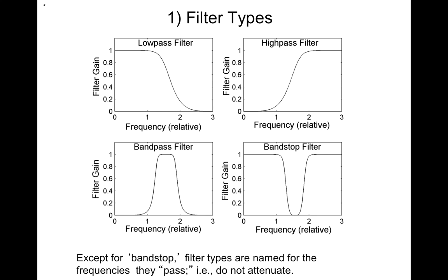Why would we want to use different kinds of filters? Turns out that a lot of times signal noise occurs either uniformly over all frequencies or will have more high frequency characteristics. So a low pass filter is often used to increase the signal to noise ratio and get rid of noise issues in the filter. Whereas the high pass filter, notice, will zero out DC or very slowly varying components. So the high pass filter is often used to eliminate DC or to eliminate drifts in the DC due to changes in your ground voltage that occur slowly.